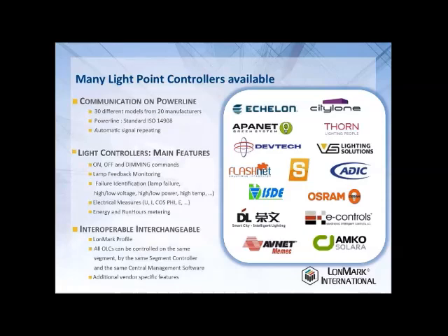It provides also lamp feedback monitoring, really the status of the lamp, including lamp failure, high-low voltage, high-low power, high temperature, low power factor, and so on. Most of these devices provide also voltage in volts, current in amps or milliamps, power factor, energy, cumulated energy in kilowatt hours, number of burning hours, power in watts, etc. And some of these devices are even providing more.